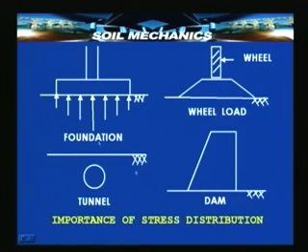Let us take a look at these four diagrams. The first one is that of a foundation resting on a soil. Let us try to discuss this a little bit. Suppose there is a foundation which is subjected to a load from above, from the superstructure. Strictly speaking, the foundation will distribute the load to the soil in any manner it chooses, depending upon the foundation and the soil. It is very difficult to predict what will be the pattern of distribution below the foundation.